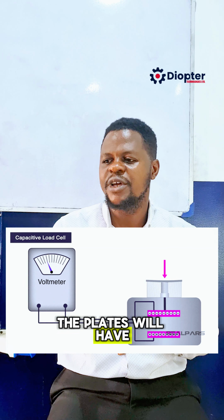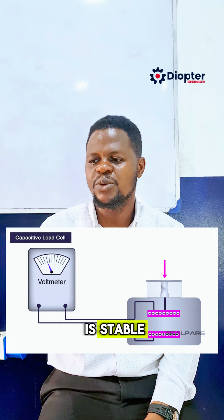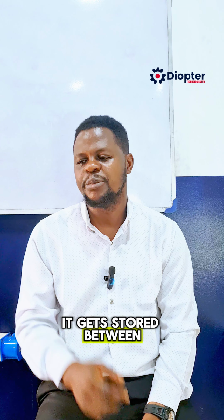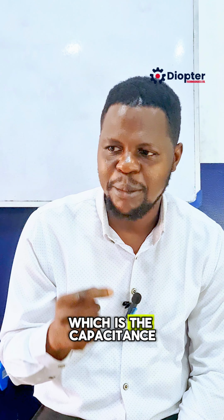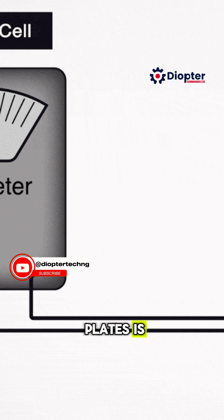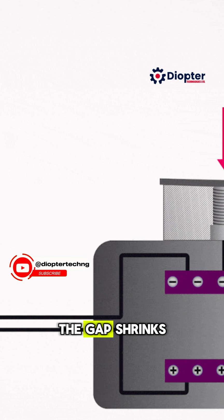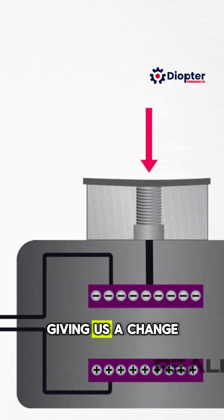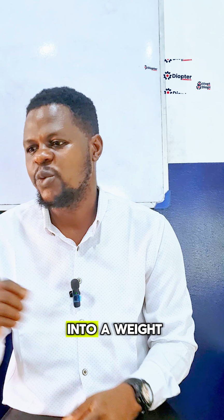The plates will have a current applied to them, and once the charge is stable, it gets stored between the plates. The amount of charge stored, which is the capacitance, depends on how large the gap between the plates is. When the load is placed on the plate, the gap shrinks, giving us a change in the capacitance, which can be calculated into a weight.